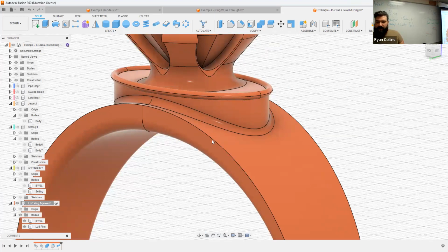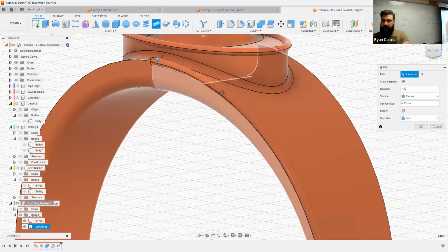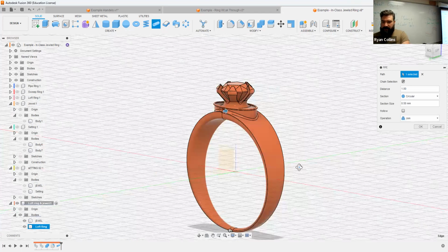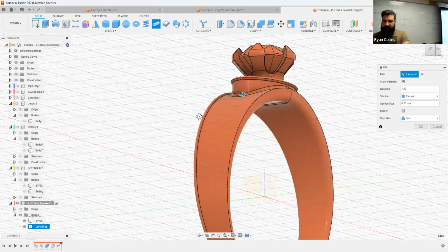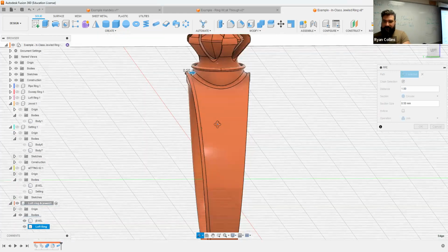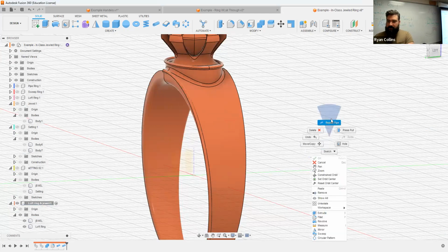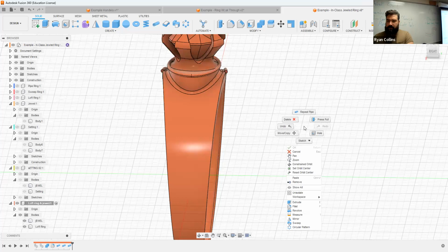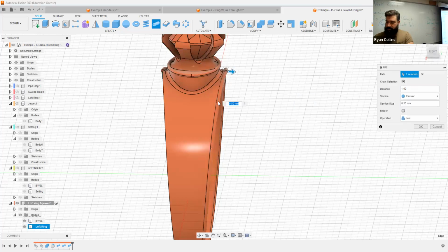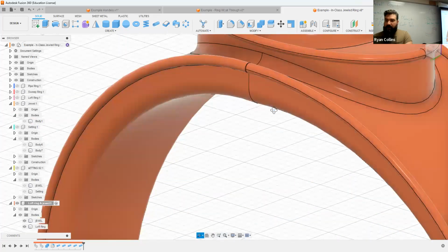You can do the same. Maybe I want to create around the ring itself. Oops, sorry, wrong way, zooming. Now you can only do one at a time. It won't let you select multiple paths, but you can see how I use the path along the edge of that line there. Same thing. So I can create multiples, and I'm just right-clicking to repeat. Repeat pipe, select that edge. Same. Orbit over, select that edge. Same. And last one, right there. So you can use the pipe tools and sweep for that matter along that.